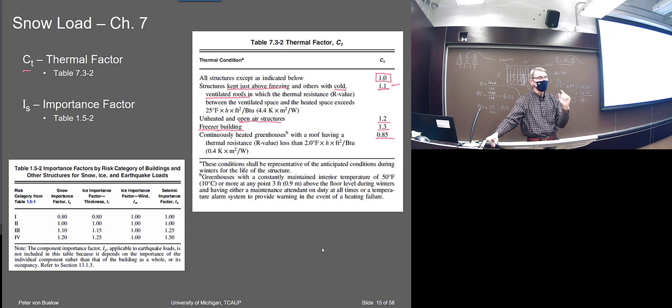Go on a sunny day, the sun's coming through, and they deliberately make all the glass single pane. And you could think, well, why don't you make this thermal pane? You're losing so much energy. Well, because they want it to heat the glass and melt any snow that gets on there. If it were thermal pane and it snowed and the snow didn't melt, it would suddenly be dark in the greenhouse, right? You wouldn't have the light coming through. So they deliberately make it so the snow melts off, and that gives it a different value there.